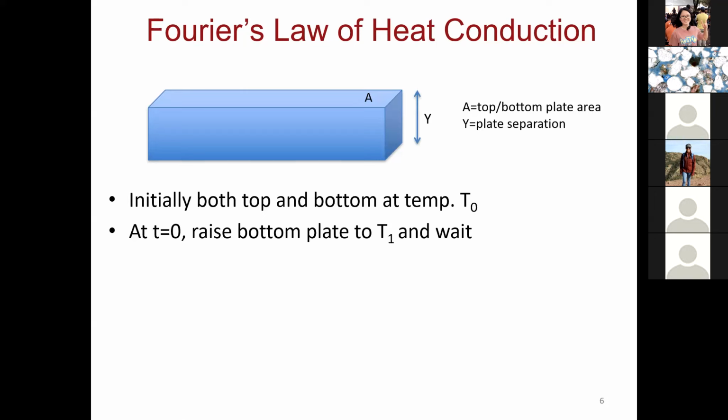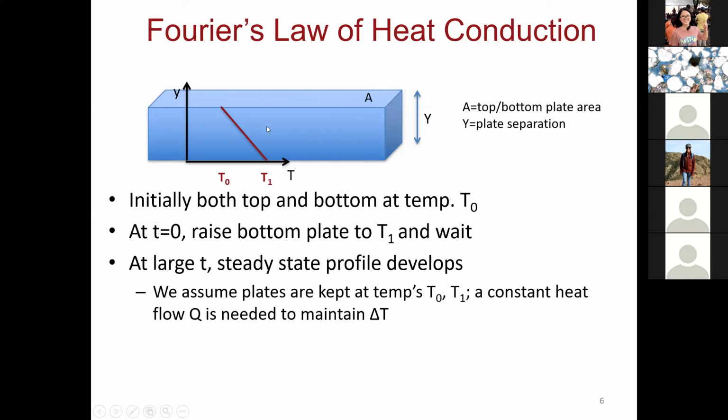Okay. So after some time, initially I'm going to have higher temperature here, and because of the energy transfer in this cross direction, eventually most of this thickness will heat up, assuming that I keep this temperature at the bottom. I have a heater that is keeping it at T1. Eventually, I will actually have this linear profile that basically goes from temperature T1 on the bottom to temperature T0 on the top. Okay. This I think is something that is familiar.